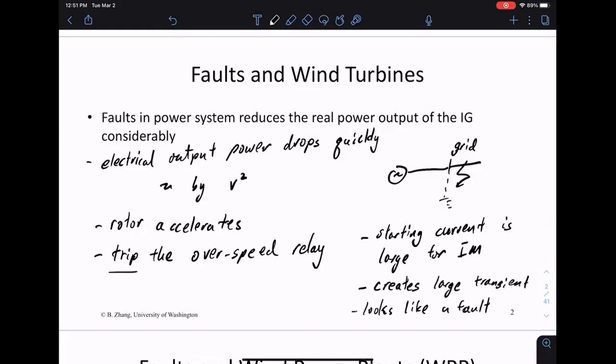Okay, so if the wind turbine is large, especially, and you connect it to the grid, then for a grid that just recovered from a previous fault, we just cleared the last fault, now there's a lot of current coming again. That creates other problems in the grid, right? So you don't necessarily want to just kick your turbines offline whenever you see a fault in the system.